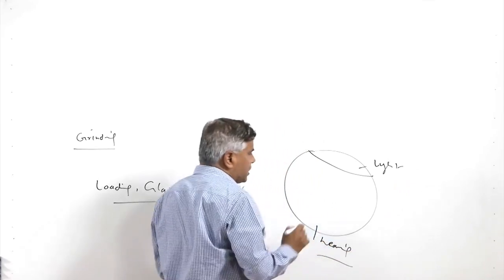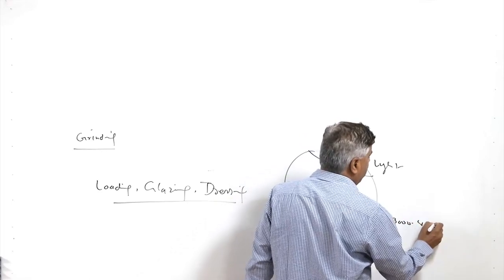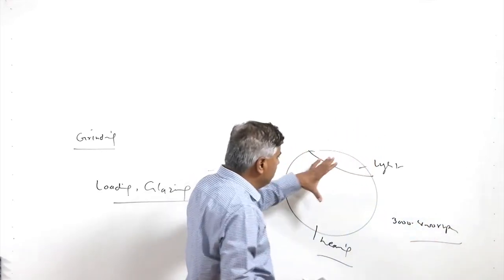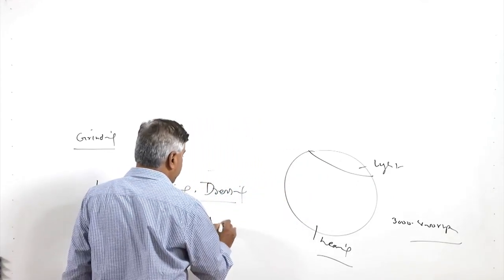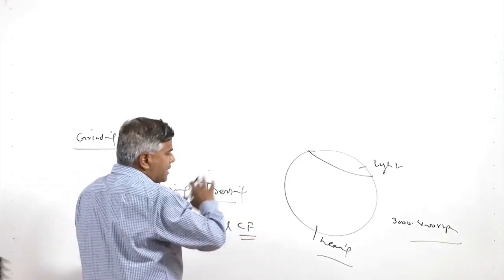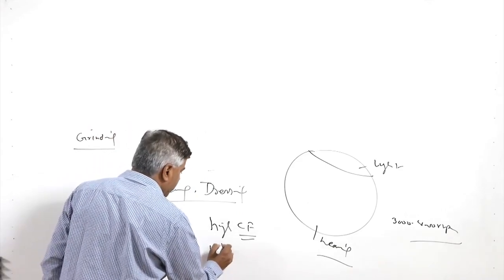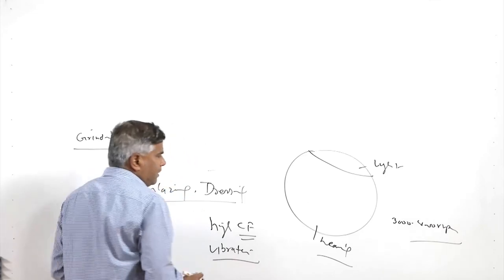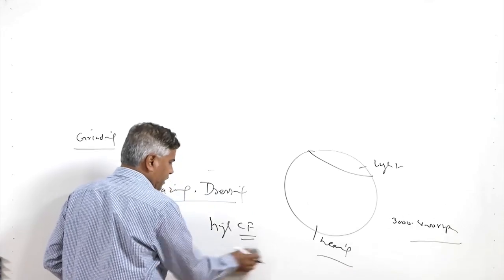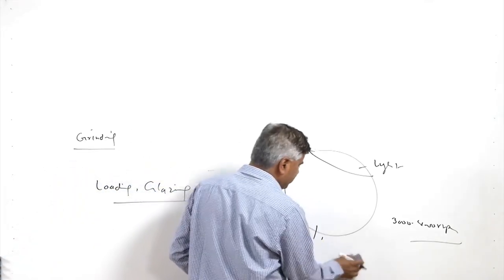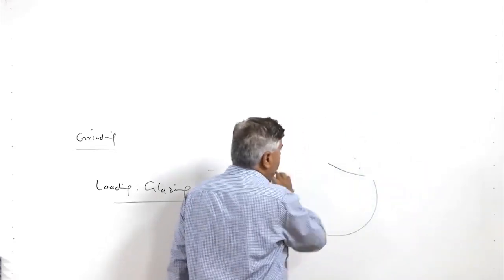So, during the rotation at much higher speed, maybe like say 3000 to 4000 rpm, under these conditions even a little bit of imbalance in the grinding wheel will lead to high centrifugal forces. So, high centrifugal forces will generate destabilizing forces that will lead to vibrations, and may even lead to the instability of the grinding machine which is being used. So, that will lead to unnecessary noise, reduced surface finish, and heavy vibrations due to